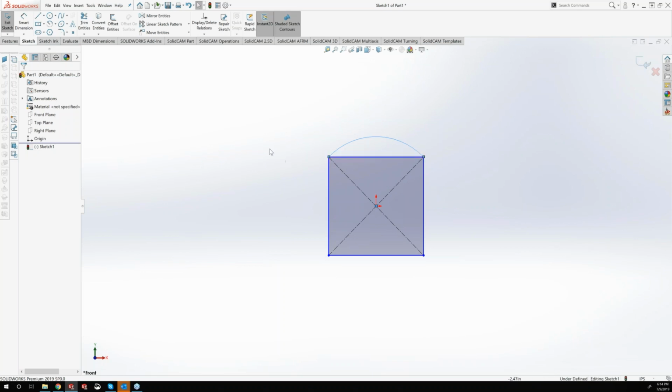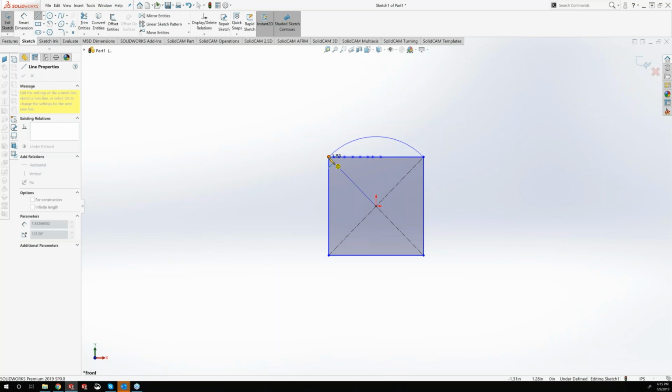looking to cut. So what we try to do by breaking it up with that interpolation check box is we're going to come in and put in a ton of points along this line. And the distance between those points is going to be that tolerance value that you see in that checkbox. And so what that does is it allows our X to be the function of this radius here, and it's going to be output at all these locations.